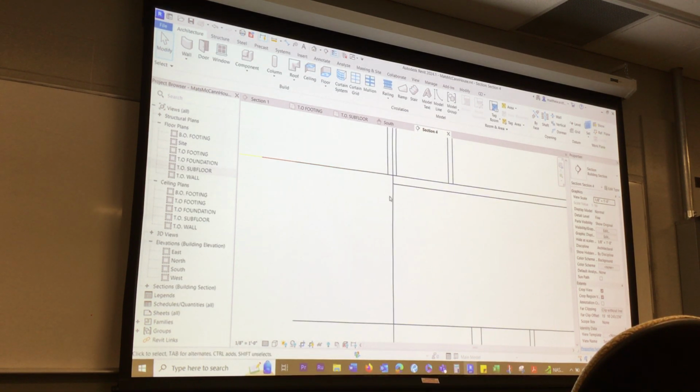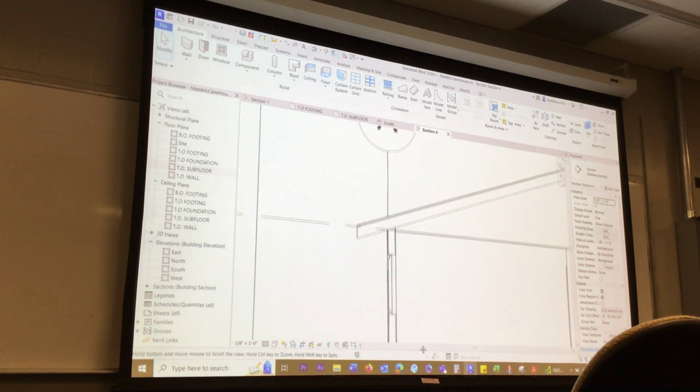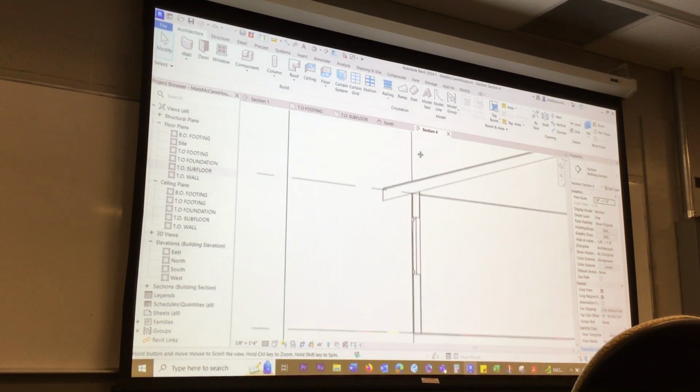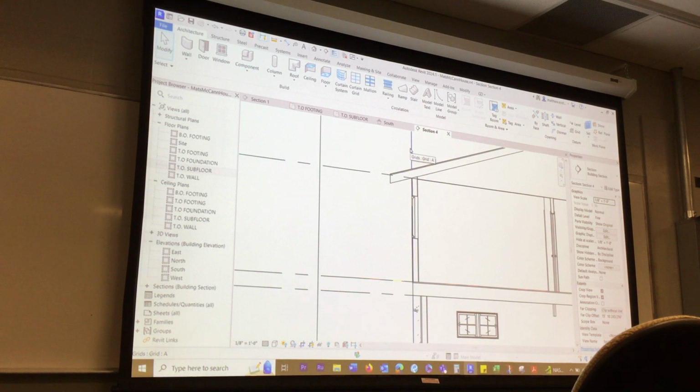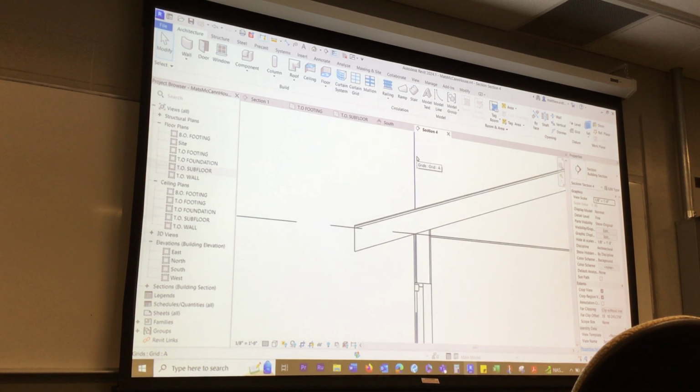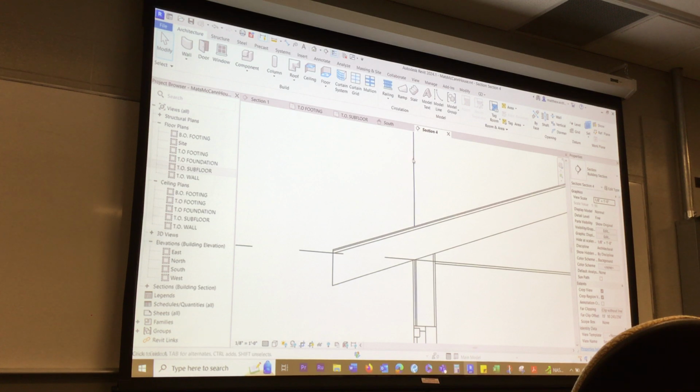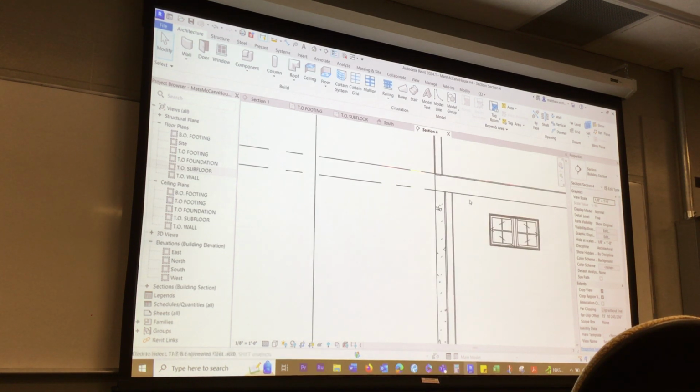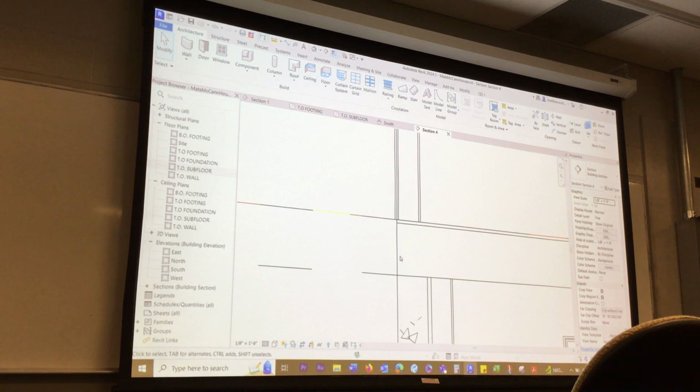Okay, so there's my grid line right here. If I light that up, and everybody's file, this is what I do, both directions. I put my own section in and I check it. So that's got to run right down the sheathing where it does. You can see it lighten up that wall, right? And then I've got everything else lined up to it. The floor goes to outside of sheathing. Many of you went to the outside of the siding. Has to go to the sheathing, otherwise the foundation's too big.